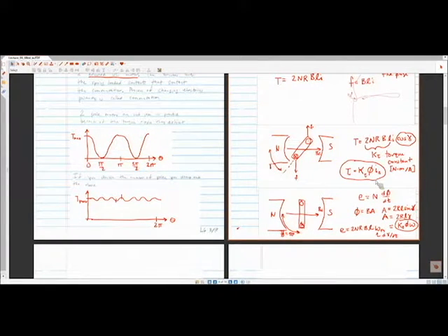And then we talked about the back EMF. So the back EMF, as a reminder, is based off Faraday's law. This is the voltage that's created in a coil whenever you have something rotating through a magnetic field or moving through a magnetic field, right? And so we said this is given by Ka phi omega.